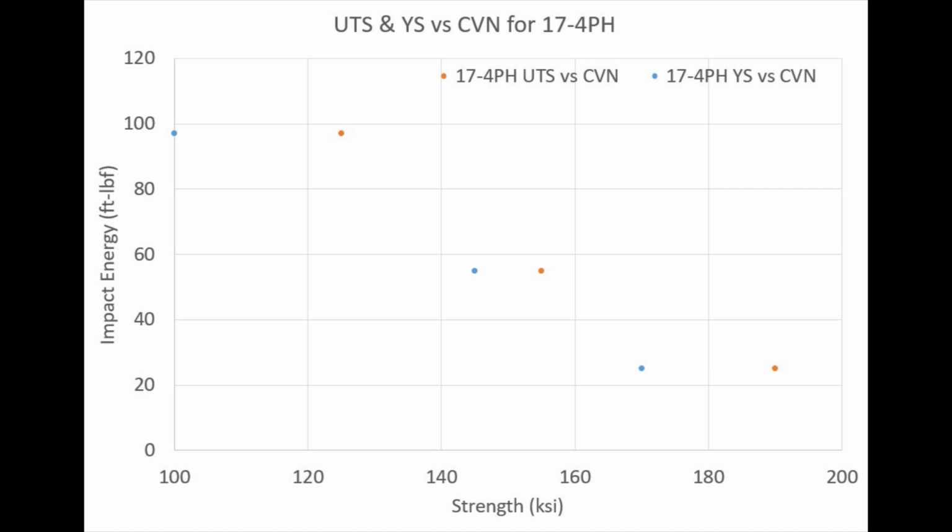So in the case of, let's say, aircraft, for example, aircraft are notorious for experiencing fatigue cracks. Making sure that a crack doesn't hit a sufficient size that a part breaks, you'd want to have sufficient strength and then maximize your toughness to make sure that you're far enough away from hitting what's called the critical flaw size. But the concept of toughness is really important wherever you go.